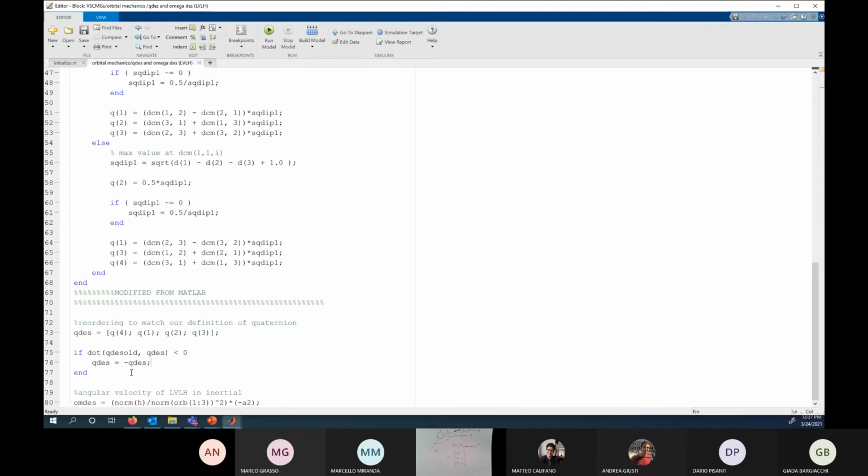So it's just a sanity check to make sure that you're not, because this may happen from this function, commanding all of a sudden, before you were commanding, okay, rotate about this axis 5 degrees, and then the next step is rotate about this axis 355 degrees, and you go all around to obtain the same orientation. That's it. So that's basically what this is preventing, okay?